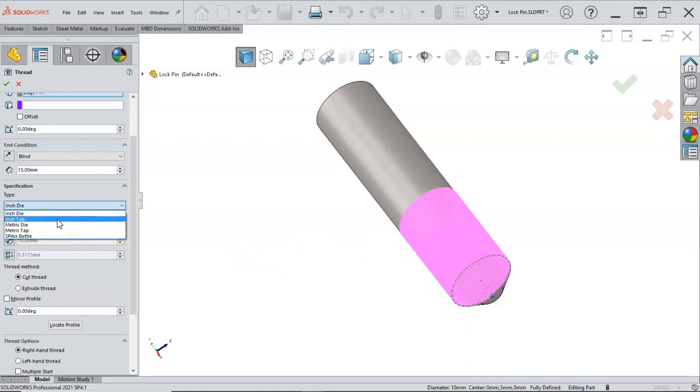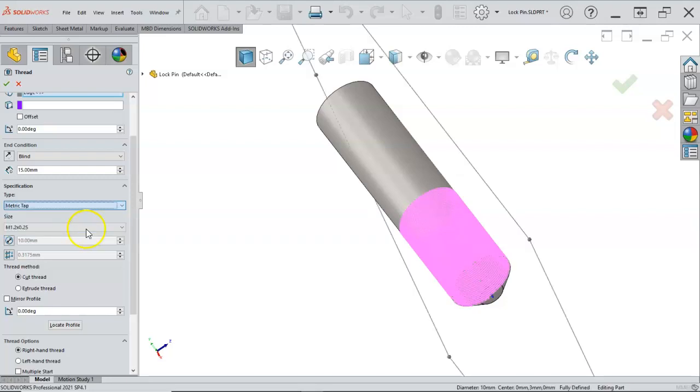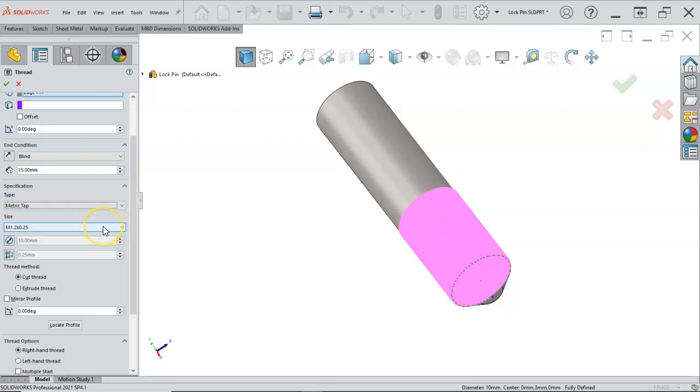The tap then is what we're going to do to cut internal threads, and we select the taps and the tap drill based on the chart and the information we just went over to create either the mating geometry or picking out a nut.